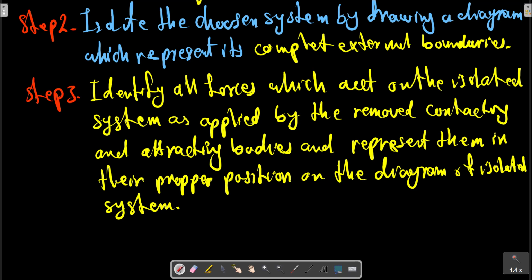The subsequent calculation with the equilibrium equation will yield a positive quantity if the correct sense was assumed, and a negative quantity if the incorrect sense was assumed. It is necessary to be consistent with the assigned characteristics of unknown forces throughout all the calculation. If you are consistent, the solution of the equilibrium equation will reveal the correct sense.